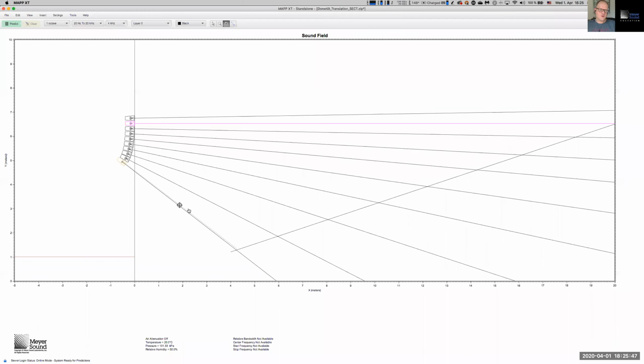By default, the rotate tool puts the center of rotation in the middle of the line segment, but remember, I'm free to put the pivot point anywhere I want. This time I'm going to put the pivot point once more at where that line segment starts in the audience. And again, I can now rotate this line segment as the dial of a clock. And I'm going to make it level like I did before without actually pivoting or orbiting the loudspeaker, but it still gives me a measure of distance, which is what it's all about.